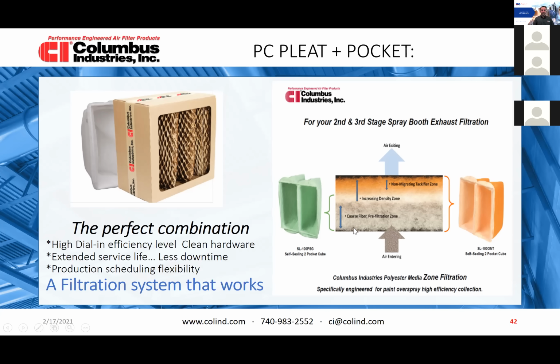Okay, and this is done through zone filtration, through using non-migrating tackifiers, and using other technologies like needling to consolidate or condense the particles, the layers in here, from here to here. For example, this filter does have the tackifier. This one is dry. Again, it depends on the particle. If it's a particle that's dry, this is what we use. If it's a particle that's very, very fine and still a little bit wet, but extremely dusty, this is what we use. So it's a filtration system that really works.